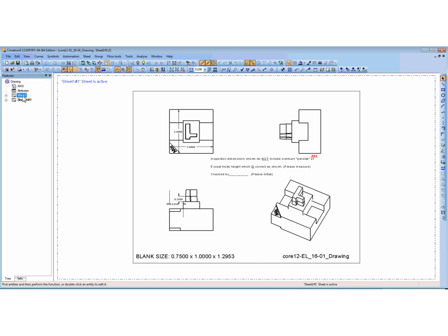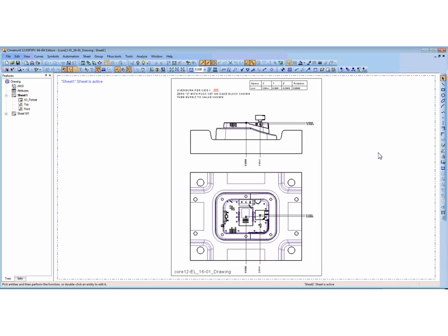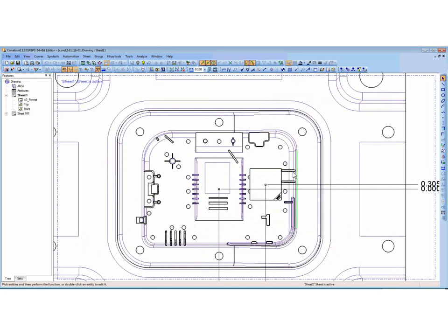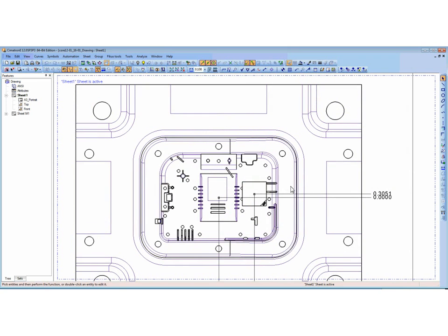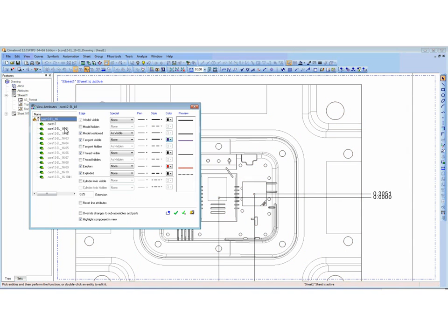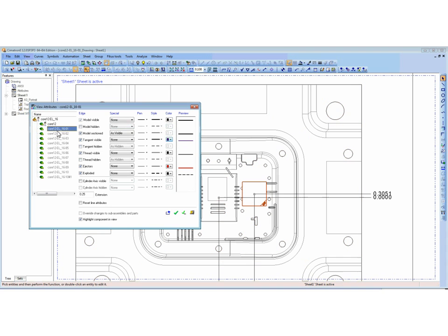And there's also a burn drawing. So this would give you a view of that electrode in the front view. Again, you've got a chart for where it's going. And we can even add hidden line attributes to it. I always like to show this as well. So here, I'm going to ask that the core have hidden lines, and they can be a dash gray color.